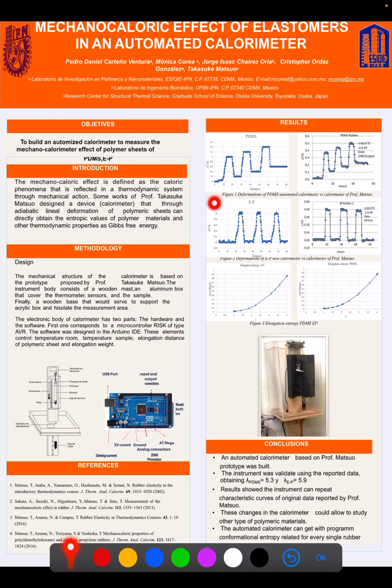For the first case, we could observe that for polydimethylsiloxane, while time is increasing, temperature is increasing under adiabatic linear deformation. But we could notice that at the end of every single adiabatic linear deformation, polydimethylsiloxane does not regress to its original parameters.